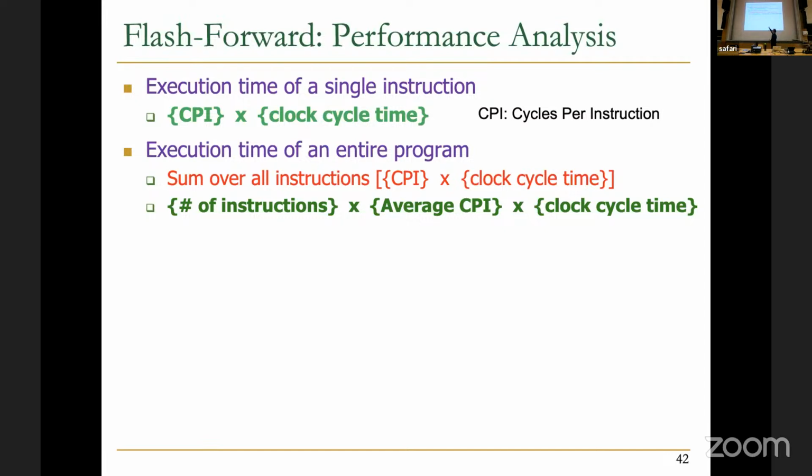You can see that you actually have different levers here. You can change the number of instructions to do the same work. That requires changing your program or how it's compiled, or changing to a different ISA. You can design a microarchitecture where the clock cycle time is high, or where it is low. Or you can design a microarchitecture where the average CPI is low. Or you can try to make all of them as low as possible. So there are 3 degrees of freedom here. Unfortunately, they're not completely independent of each other, as we will see many times later on. In fact, whenever you try to reduce the clock cycle time, almost always you're going to increase the cycles per instruction, as we will see just now in this bottom part.